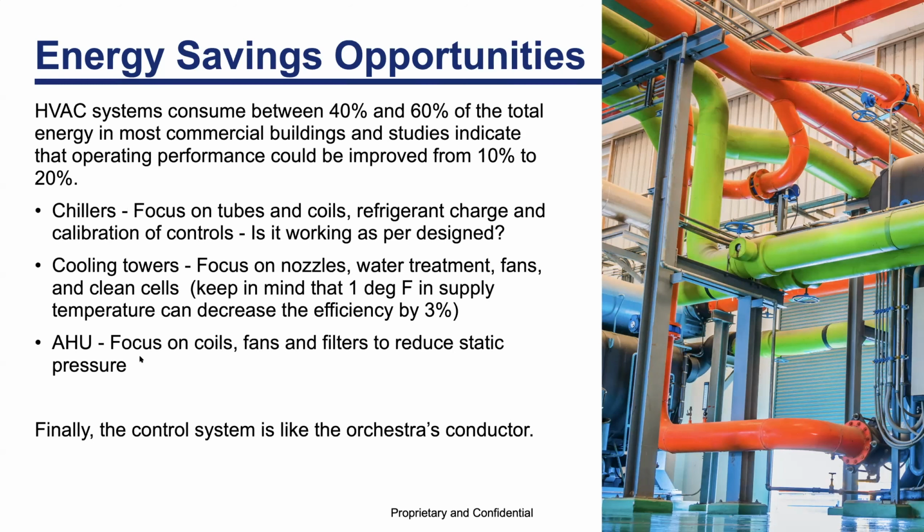For cooling towers, in addition to ensuring that water is being distributed correctly, water treatment, etc., evaluate the option of tower fan control or fan optimization. That's another terminology for that. Always evaluate the option. Don't assume that by installing VFDs on the cooling tower, you will automatically save energy. You might, but probably not as much as you expect.